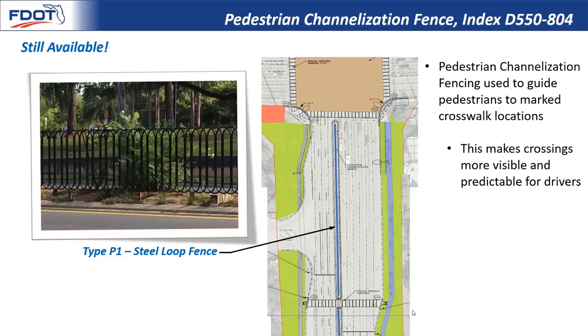And so I do always like to point out that fencing is not really a new idea. A fence is not a new invention, and so there's a reason it's rarely been used on medians and roadways in prior decades. Basically, a fence is considered a sight obstruction for vehicles. A fence creates an additional obstruction on the side of roadways for errant vehicles to possibly run into. Fencing increases walking distance and can make pedestrian travel less efficient. The installation of pedestrian fencing can be expensive. And last, the maintenance cost for fencing can be expensive if it's frequently hit by vehicles, particularly for this high-cost custom fence that's made out of solid steel and designed to prohibit climbing.